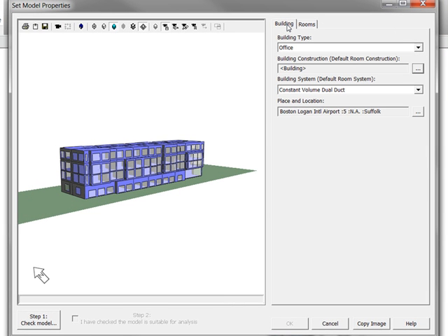But the most important thing, if you're looking for comparison models with a tool like Gaia, is that you have a baseline model and you keep it fairly standard, so you're changing only one thing at a time. You're not going to say, my first baseline had this many square feet or square meters, then I changed my glazing and my wall construction and I changed the building form, because that's not going to give you an idea of the ramifications of each single change.